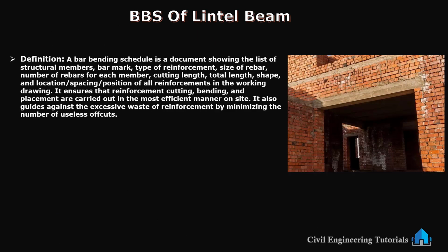So here you can see this is the lintel, or you can say lintel beam also. So first the definition. A bar bending schedule or BBS is a document showing the list of structural members, bar mark, type of reinforcement, size of rebar, number of rebar for each member, cutting length, total length, shape and location, spacing, position of all reinforcement in the working drawing.